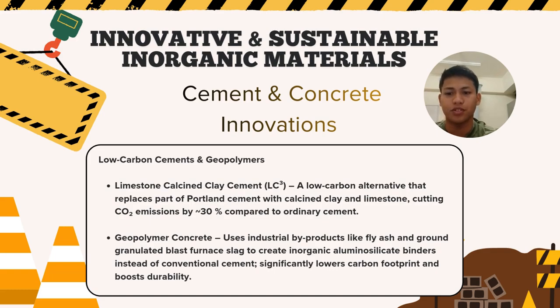Geopolymer concrete uses industrial byproducts like fly ash and ground granulated blast furnace slag to create inorganic aluminosilicate binders instead of conventional cement. It significantly lowers carbon footprint and boosts durability.